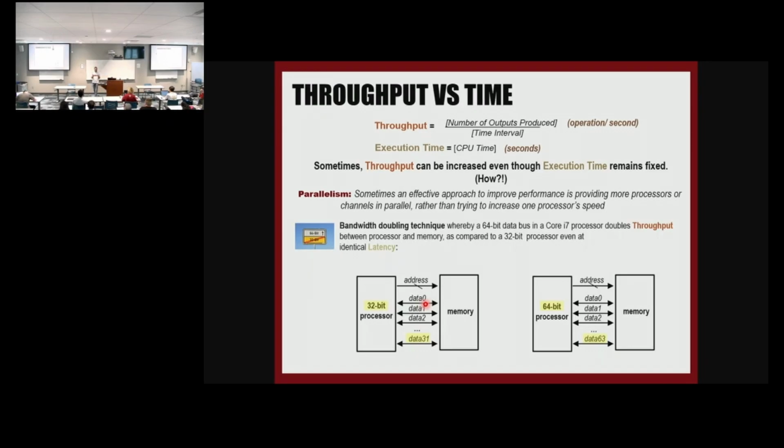They just had 32-bit add, but they could add 2 numbers that were both 32 bits, but they just made the data bus 64 bits. And it means that you send enough data to do 2 computations at the same time, right? So this was a simple thing that they did, going from 32 to 64, without necessarily changing the processor, but later they actually changed the processor too. Now, good processors actually do 64-bit multiplication, 64-bit addition, and so on, right? So this is bandwidth doubling.